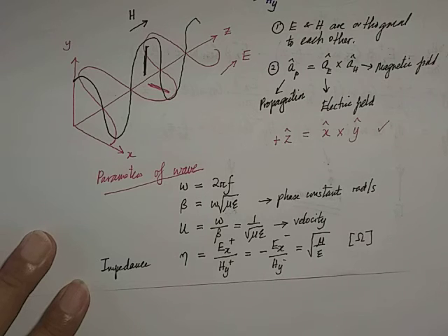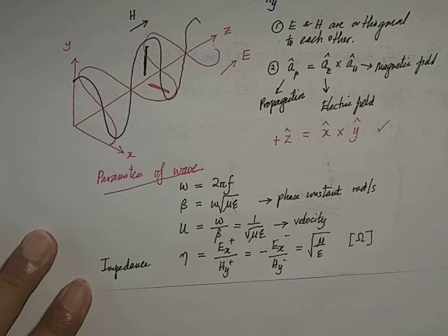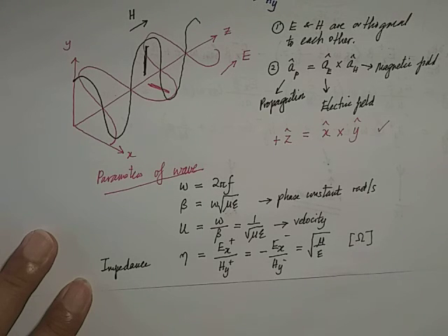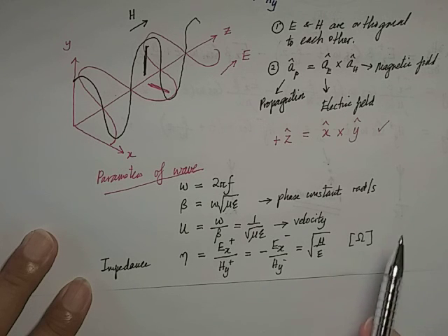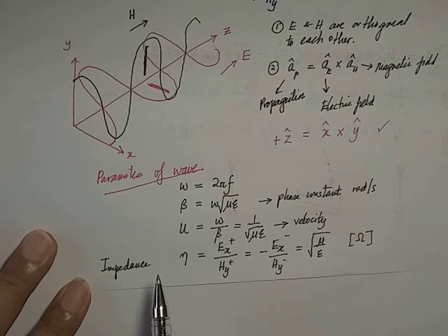So now you can see impedance does depend on the medium. For those who find impedance using resistance and capacitance, this is just a basic method, but the final impedance value depends on the material that you are using to fabricate the cable or the transmission line, because it relates to how the electric field and the magnetic field behave in the medium. So that should be impedance.